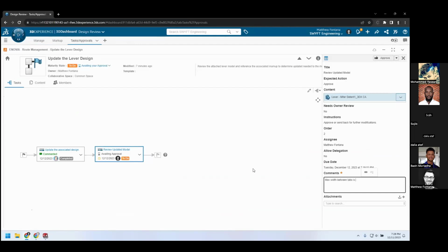And then once that has been completed, you can see up in the top right, I have the option to approve. But next to that, there is a drop down. So once I've gone through, given all the notes I want to, you could also do another markup if you wanted to. You can get as complex as you want with this. But then I can go through, drop that down, and select reject.